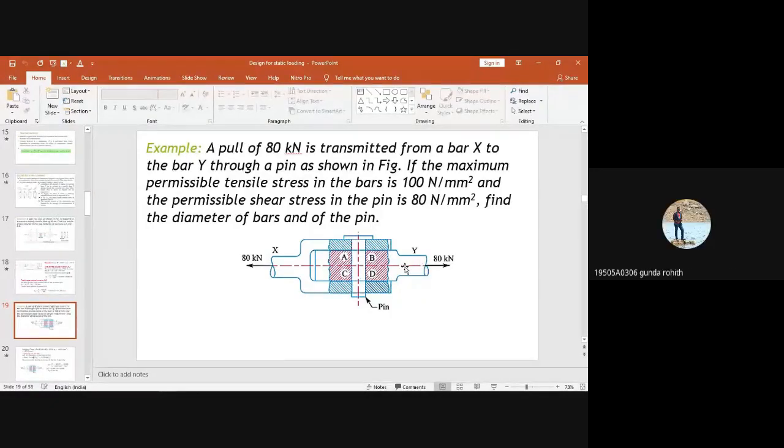Tensile, sir. Okay. Before going to tensile, we can say that it is acting along the longitudinal axis, right? This is the axis. Yes, sir. So it is acting along the axis, so we'll call it an axial load. Then we decide that if it is towards the body, it is compressive. If it is away from the body, we say tensile. So whatever is said is correct, but the only thing is, it is an axial load and also a tensile load.